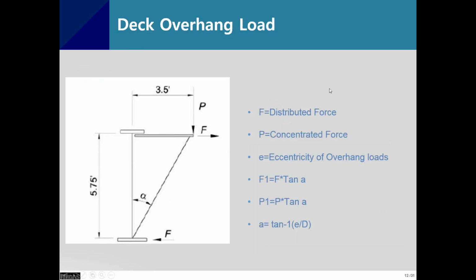And you have to tell the program the deck overhang load. So this capital F represents the distributed force. As you refer to these pictures, you can see those two F forces create a moment. So you can tell the program what F is, and Midas Civil automatically calculates the moment for you. And the P is a concentrated force. And also you have to tell the program the eccentricity of the overhang load.